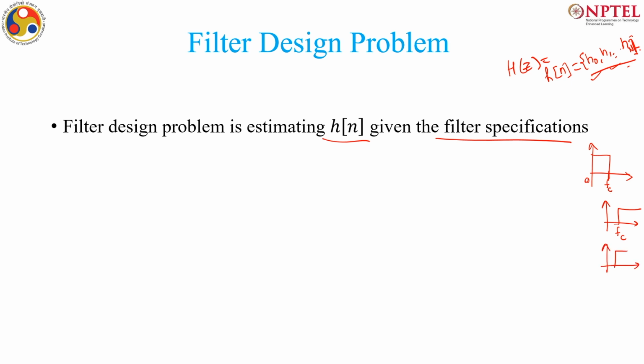Similarly, there can be a band pass filter. So this is low pass, this is high pass, this is a band pass, and these are basically very trivial things. So I am just giving you a hint. f1 and f2 are two cutoff frequencies for this, and similarly we can have a band reject filter which will reject a specific band of frequency. Band reject or band stop filter, fine.